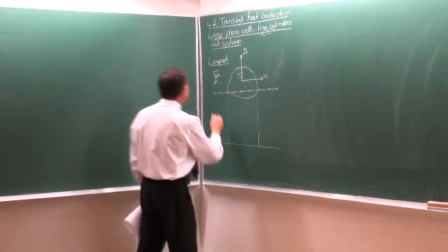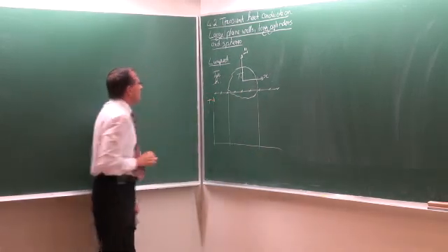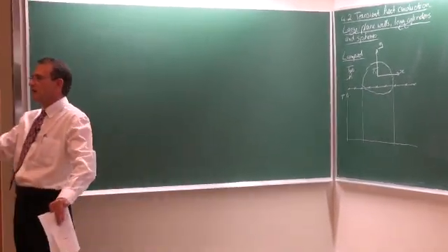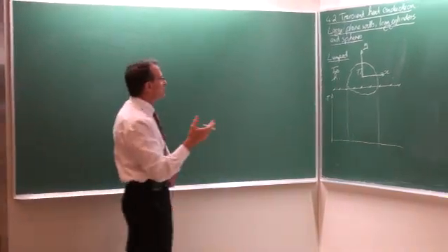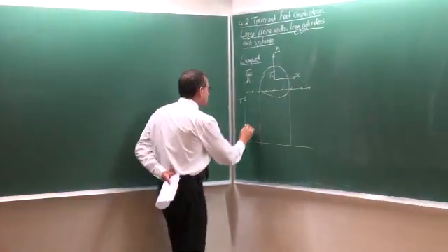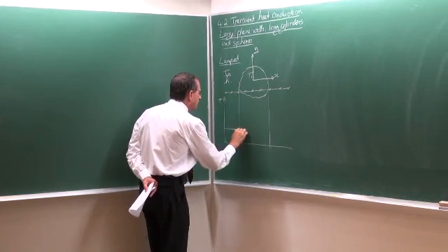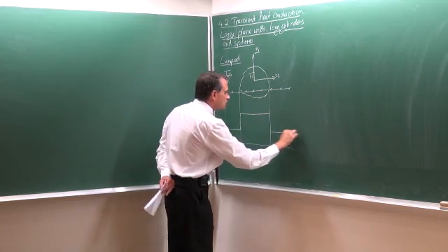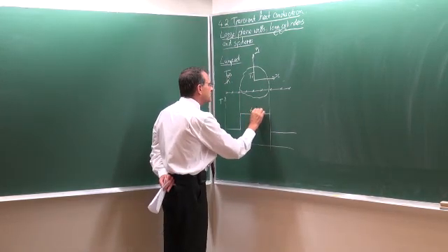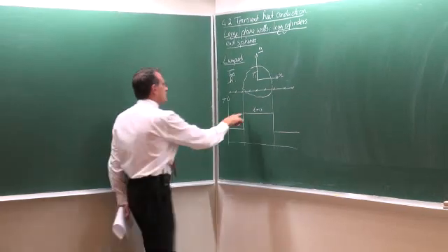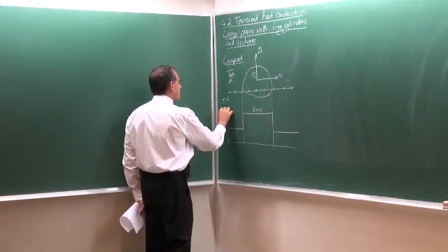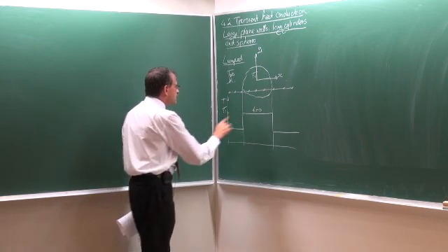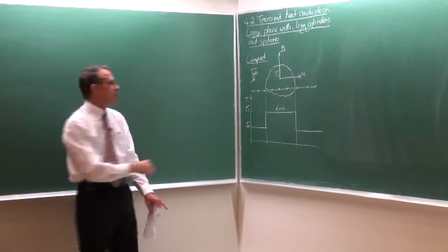Let's suppose the body is at a higher temperature than the environment, so it is a hot body which is being cooled. At t equals 0, we will have the environment temperature, and then the temperatures in the body are going to look like that at t equals 0. That temperature there would be equal to Ti, and this temperature would be equal to T infinity.